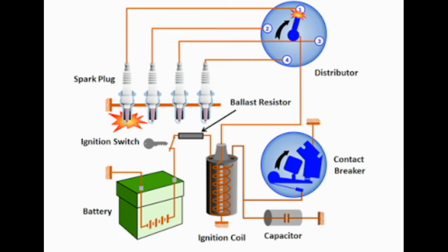5. Contact breaker. It is a mechanical device which is used for making and breaking of the primary circuit of the ignition coil. It has two metal points made up of tungsten and placed against each other. These metal points have a circular flat face of about 3 mm diameter. Among the two metal points, one is fixed, and the other is movable. The fixed contact point is earthed by mounting it on the base of the contact breaker assembly. The movable contact point is attached to the spring-loaded pivoted arm, which is electrically insulated.